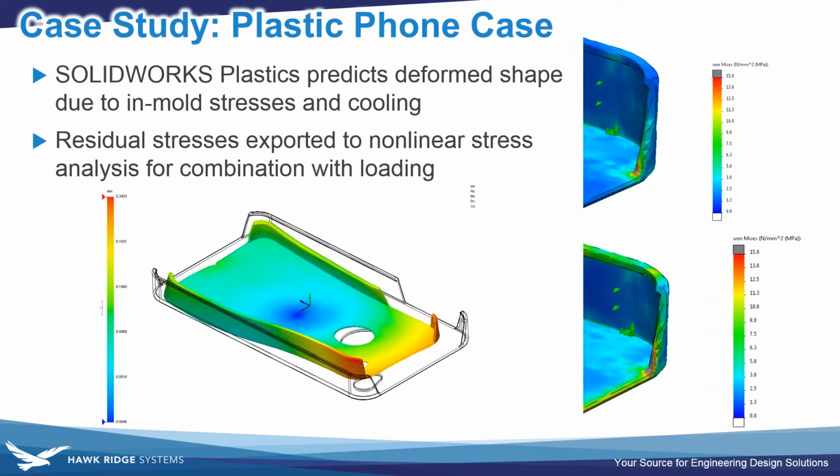But similarly to what Tim showed earlier with the C channel, that data can also help us do a more realistic loading analysis. So on the right-hand side, I've done a quick simulation of putting just a force, trying to squeeze the iPhone case, as you probably would do at a basic level in SOLIDWORKS simulation. So in this case, I've done a nonlinear analysis just to make sure that I can handle the larger deflection more accurately if I'm really squeezing that soft plastic hard.